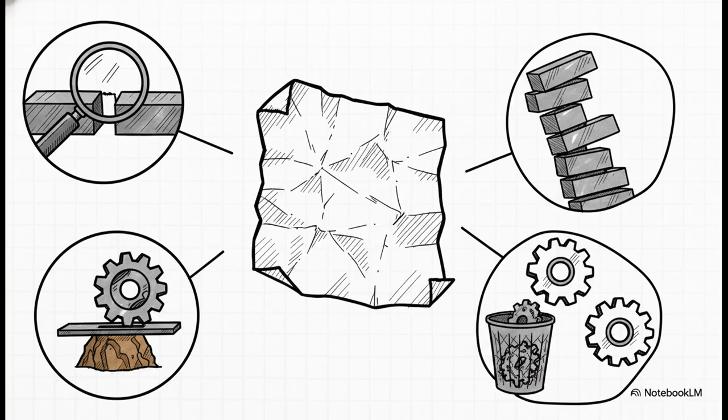Third, confusing your material condition modifiers, maximum material condition versus least material condition, stuff like that. Fourth, completely ignoring how tolerances stack up in an assembly. And lastly, selecting unstable datums that actually cause propagated measurement error. Because if your physical alignment is flawed from the start, every single measurement your CMM takes after that is going to be wrong, and you're going to end up making perfectly good parts look like scrap.